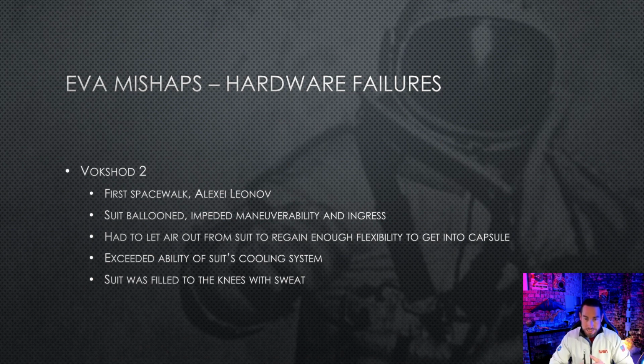This created a lot of work. It was, A, a lot of stress, but B, a lot of physical activity, because he kept getting tangled up in his tether, he couldn't maneuver. Again, your ability to maneuver independently while you're free floating in space is negligible at best. And so trying to use the tether to get himself back in, trying to fight and generate enough force to get back in through the airlock, used a lot of energy. Once he finally did get back in, his suit was filled to the knees with sweat, so he became very dehydrated, with no energy left whatsoever. And then just the problem, he's in microgravity and the suit is completely filled with sweat, so making sure that stays contained within the suit and doesn't escape out to the environment. If it escapes into the environment, then there's the potential to drown in it, or if it gets up into his helmet.